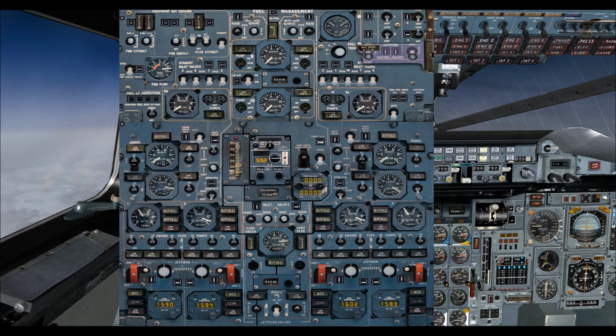Okay, we've been running this for a little bit now. The fuel in tanks 5 and 6 has moved up significantly, and in tanks 7 and 8 it has dropped significantly because we've pumped it across. And we're going to actually have to close the pumps for tank 7 because that tank is getting empty now. We're just kind of calculating in our head the weights of the two sides, and we'll stop this very soon because the two sides are balancing out.